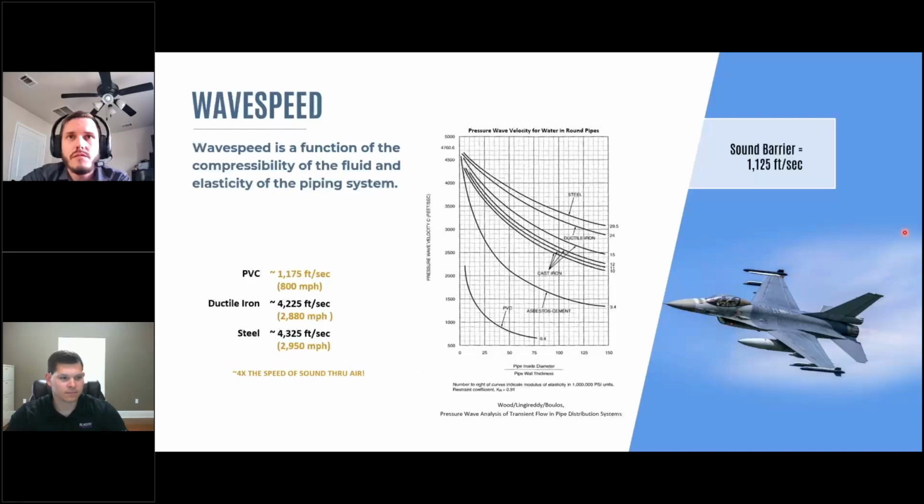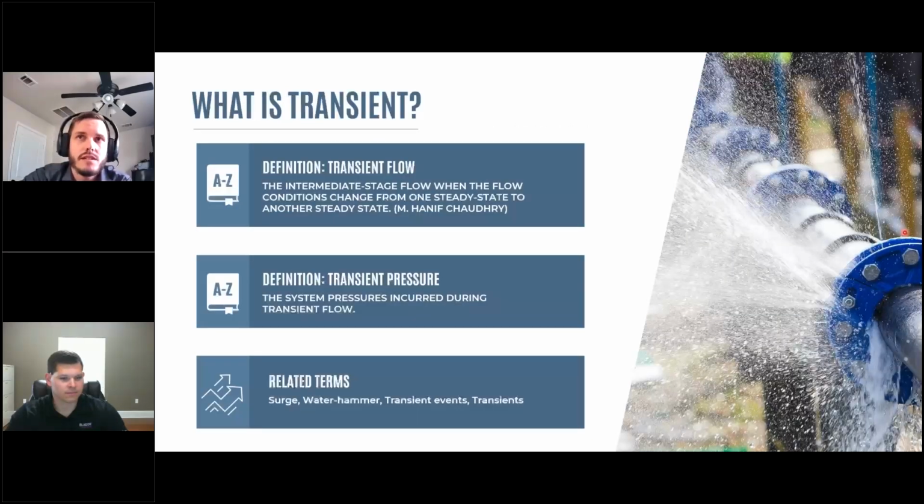The transient pressure response from initial change in velocity is characterized as a longitudinal compression wave, much like pulling or compressing a slinky. In general, the wave travels through the piping system until it reaches a boundary where it changes sign and direction. The wave comes back to its originator and oscillates back and forth until it gets dampened by friction. It's not a bulk wave where mass is actually transferred with the wave itself, such as with waves at the surface of the ocean.